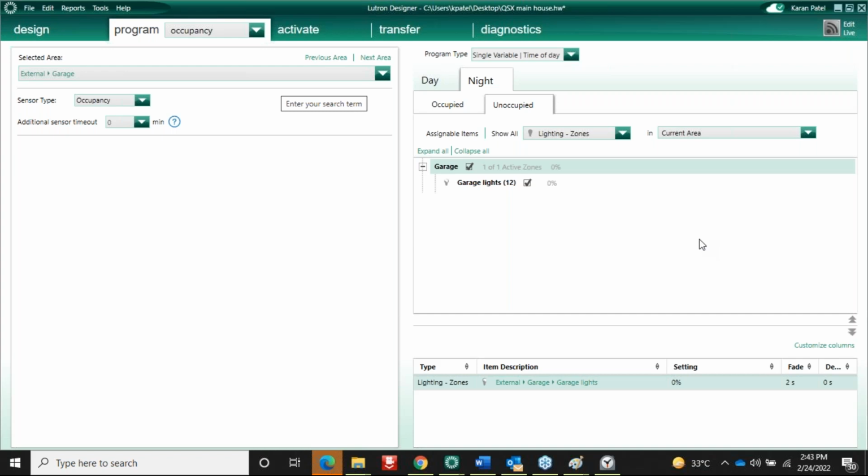DALI lights. So for DALI lights, you don't have to do anything. What will happen whenever power goes? The DALI module will take the light to 100%, because in the DALI module you give only the dimming wires to the DALI. The power is coming directly from the MCB.